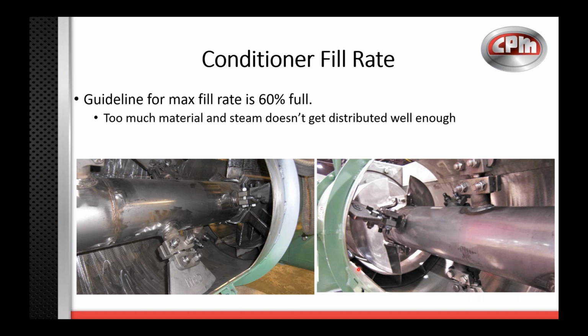I do want to point out, so this is a good picture, where our steam is coming in at. So down here at the bottom, if you can see my pointer, this is our steam manifold, and they have those little ports in there. So this is where the steam enters the conditioner and starts to begin mixing with the feed. The point of this is we have this offset a little bit because we don't want the steam to have a chance to potentially leach out and go up the feeder inlet up here, and then get into the feeder where it could cause clumps and some plugs. So the purpose is offset it a little bit. That way, as soon as it touches the feed, it's instantly being mixed.